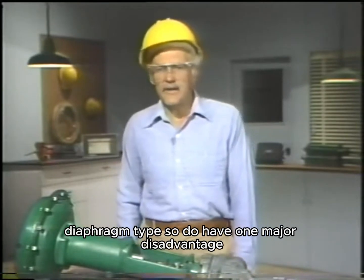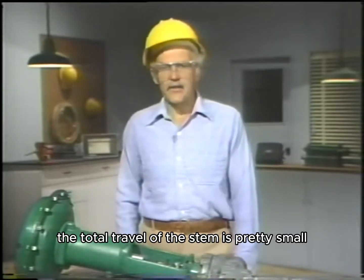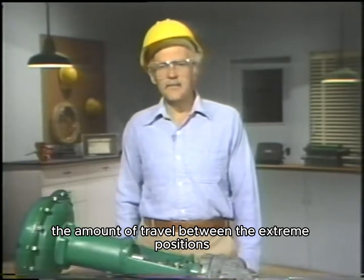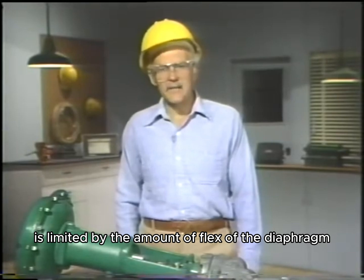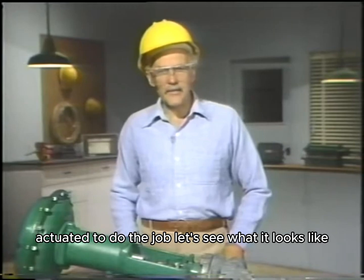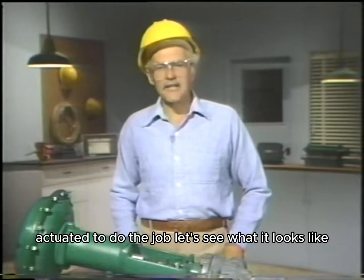Diaphragm types, though, do have one major disadvantage. The total travel of the stem is pretty small. The amount of travel between the extreme positions is limited by the amount of flex of the diaphragm. When more travel is required, there's another type of pneumatic actuator to do the job. Let's see what it looks like.